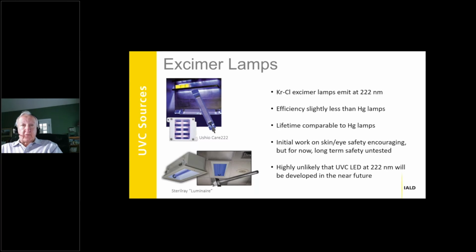Also, they're very specific to given wavelengths that you want to be able to measure in the UVC. Finally, even when a UVC dosimeter can claim to be cosine corrected, frequently it's not very good at measuring UVC radiation coming in from the sides. And it's possible to get wildly varying doses from different kinds of UVC radiometers. So just keep that in mind if you're going to start taking a look at certifying UVC sources for germicidal applications. You have to be very careful about measuring the dose properly.